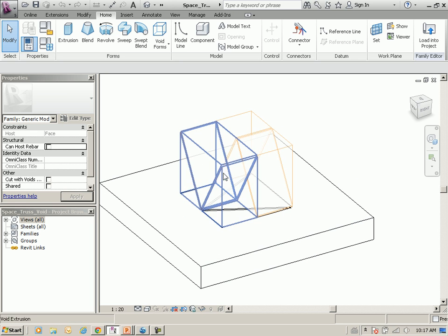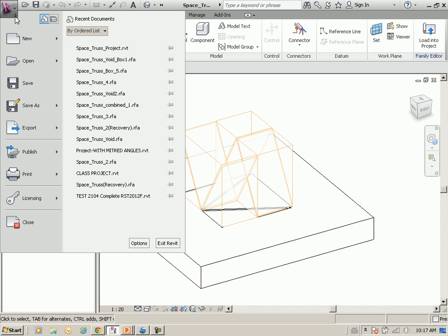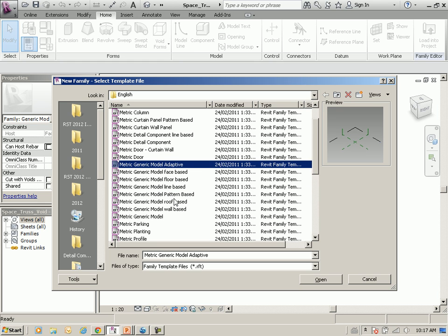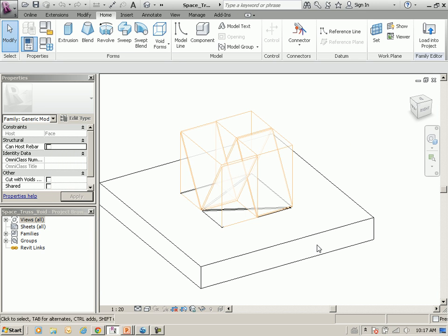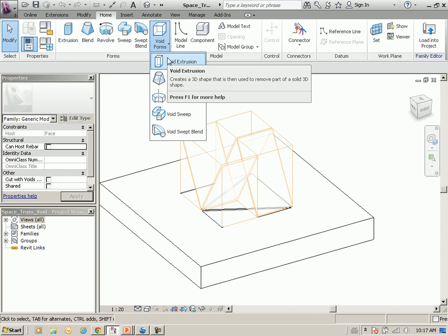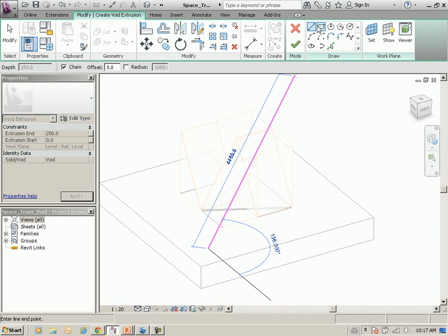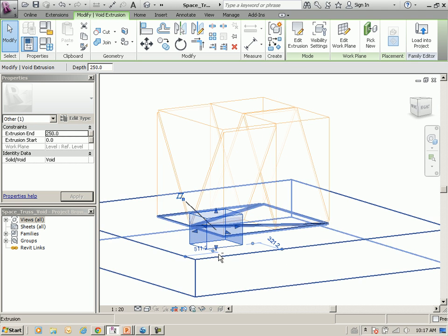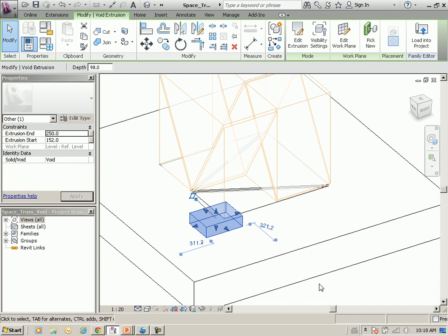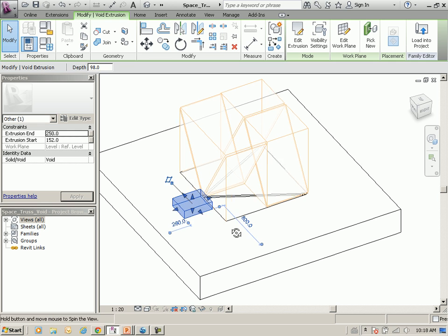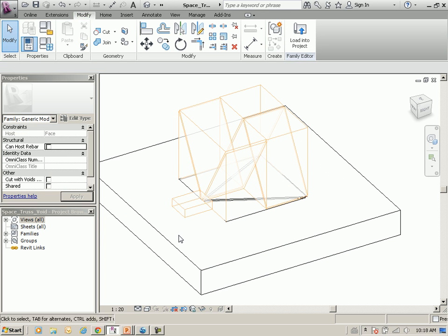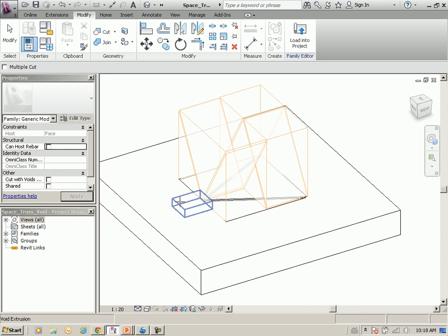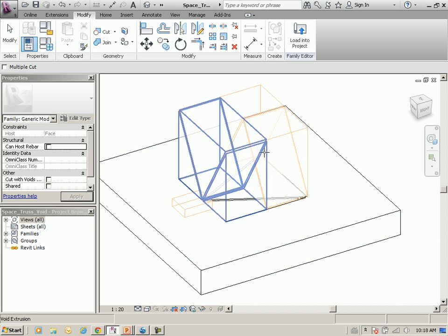Now in order to make this and make sure that it actually cuts, I'll just show you the template that you need to use. It's a very commonly used template. So you just go to this face-based one, and you're going to get a little host. And the key here is you want to make sure that whenever you make a void object in here, no matter what, even if it's not actually inside the host, so let's say I have a void right here, and I'll just click on it and bring it right outside, it's outside of the host, as you can see. This has the ability to cut its host, but you have to tell it to cut its host. Now, even though it doesn't look like it's cutting it, if it ever comes in contact with the host, it'll know to cut it. And that's how you get this thing to happen.